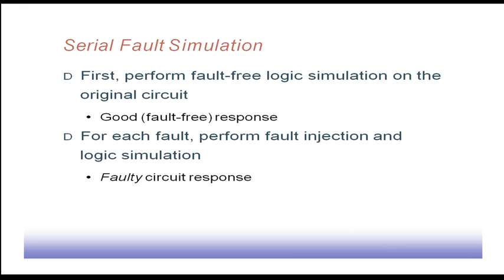The simplest fault simulation technique is serial fault simulation. What do we do in this case? We first perform a fault free logic simulation on the original circuit. We have the test pattern set, and for that test pattern set, we want to determine what the fault free responses from the circuit are. These are called good or fault free responses.